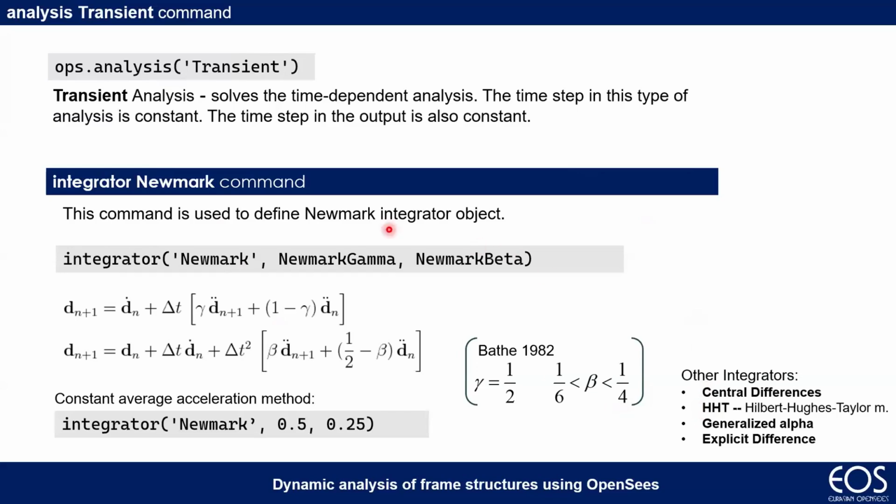The one that is typically used for this type of analysis is just Newmark. You know that you have to declare 2 parameters, gamma and beta. Typically gamma is 1/2 and beta is from 1/6 to 1/4. If you use 1/4, the analysis is unconditionally stable. So I strongly suggest you use 1/2 and 1/4. In this case, it is unconditionally stable, regardless of the dimension of the time step. Otherwise, you can use the integrator that you want, but pay attention in that case.